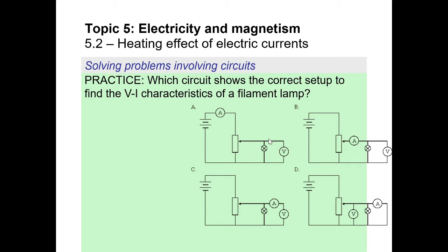So part of the current will travel up this line and the rest of the current will continue down. The very fact that it splits means the total current that A originally measured is not going to be the same current that goes through X and then eventually joins with the original split current and comes back to the source. I shouldn't say halved, I should say split, because it really depends on their resistances. I'm going to show you C next.